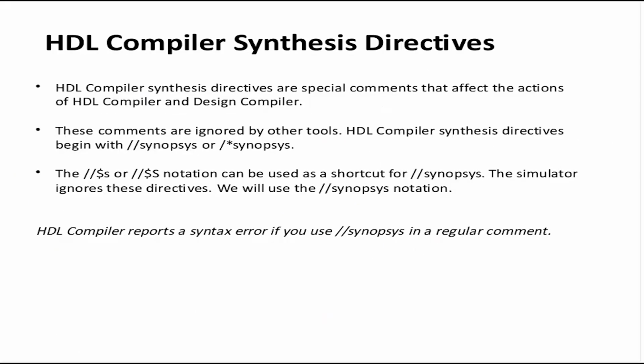Now let's look at a very important concept: the HDL compiler synthesis directive. What is a synthesis directive? These are special comments that will affect the action of HDL compiler and Design Compiler. These comments are ignored by any other tool, so they look like comments, but they are special comments. They begin with // synopsys. There's one more notation, but we will use this // synopsys notation in all our examples.